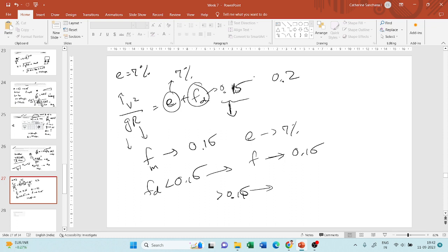Now what will I do? I have fixed the maximum limit for super elevation as 7%. I fixed the maximum limit for lateral friction as 0.15. Even after I have fixed the maximum values for all the possible elements, it is still not enough to satisfy this skidding criteria.